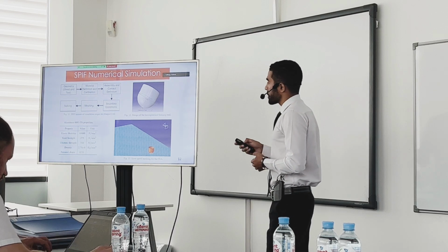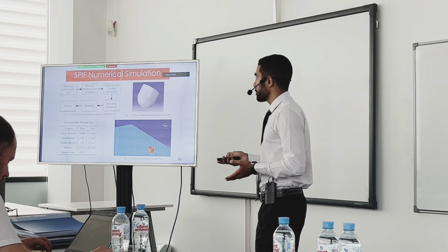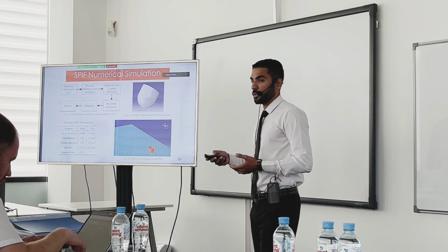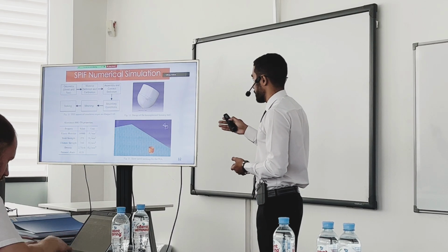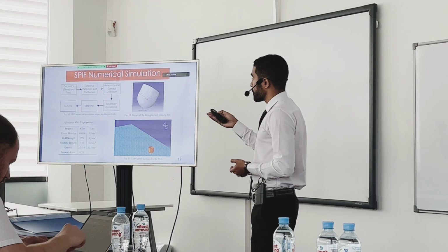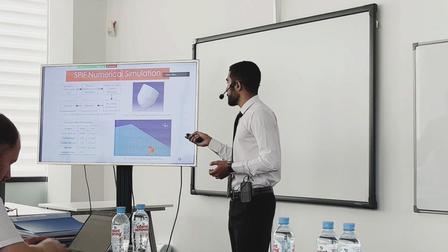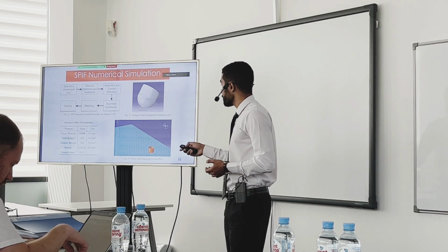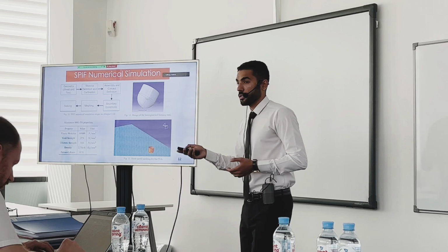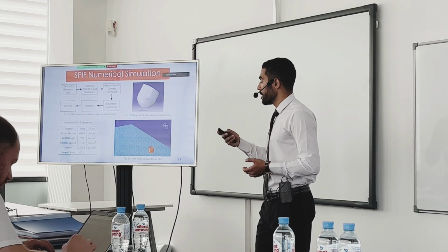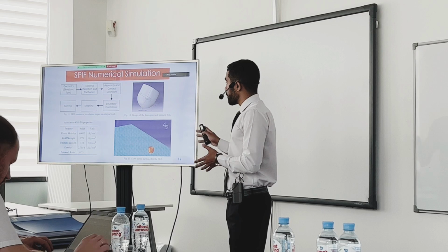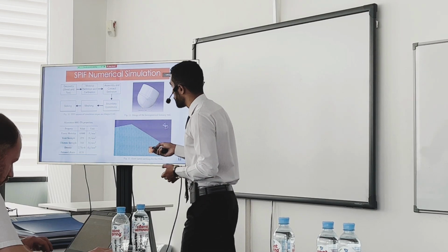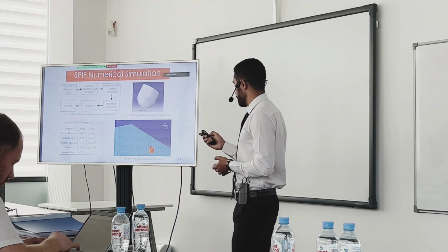So after that, it was time to perform the numerical simulation analysis. And in order to perform it, you have to go through some stages, starting with the geometry and sheet, the material definition and calibration, and the assembly process, as you can see in figure 13, and setting the boundary conditions, and then the meshing process, and after that, the post-processing. For this task, the material used is aluminum with the listed mechanical properties.